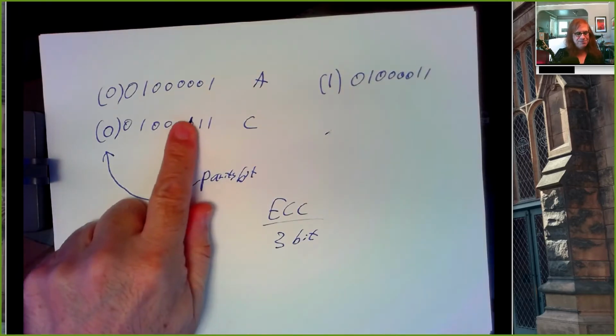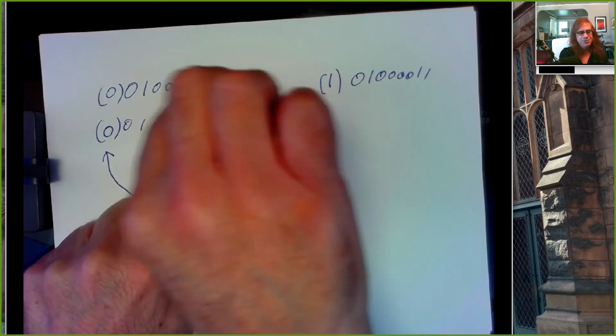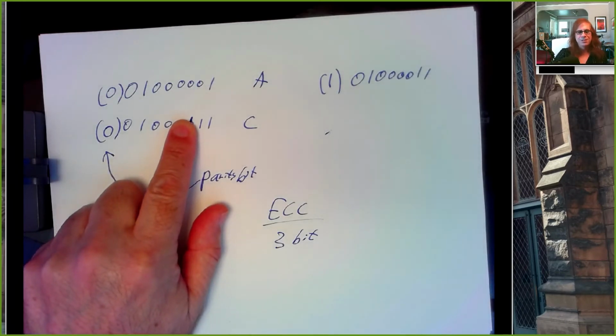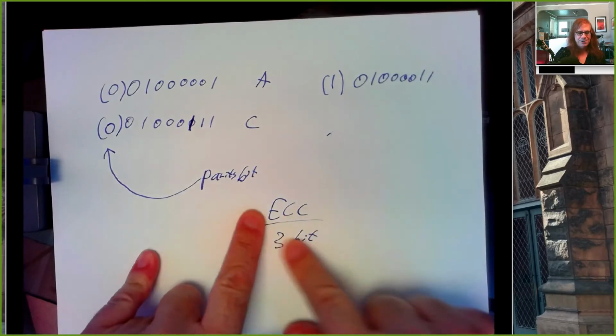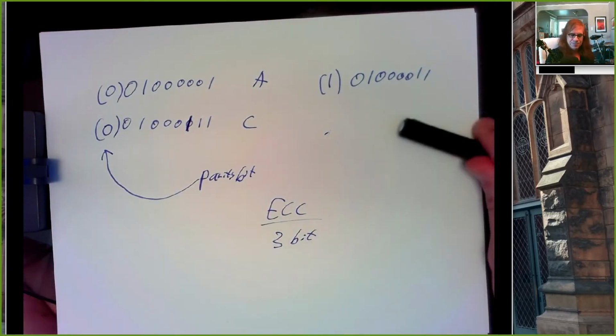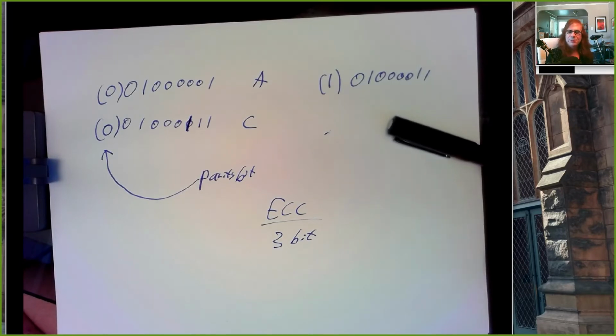And even if I have 1 error, it'll notice that something's wrong, but it has no idea which bit is wrong. It just knows that something is wrong somewhere. These more modern systems can actually reverse the errors so that you don't have to retransmit them. And so you find this used in storage systems, hard drives, things like that.